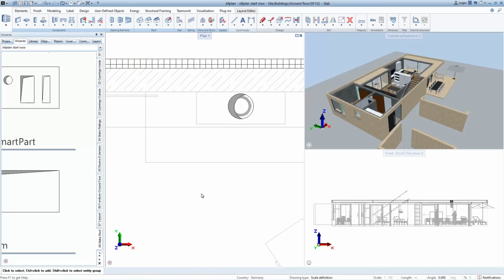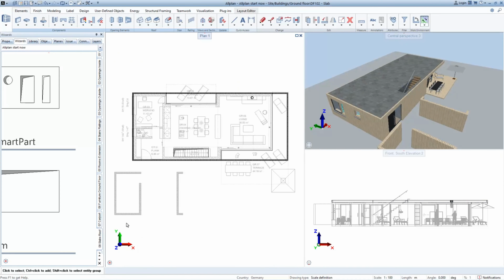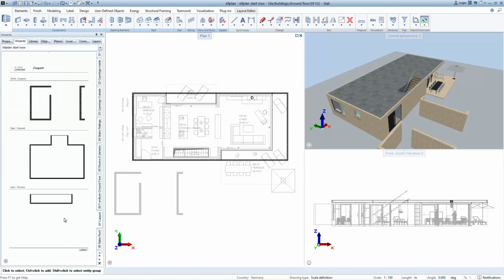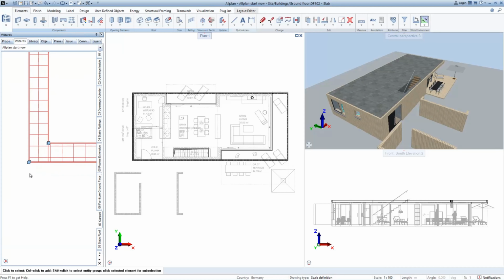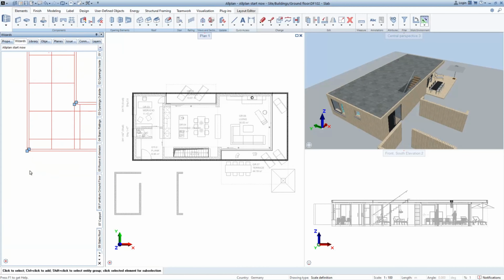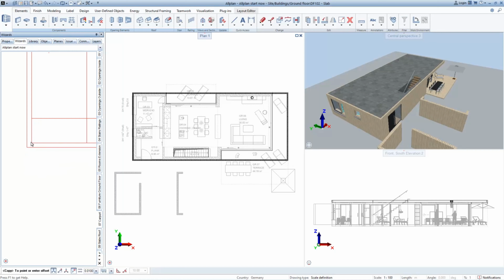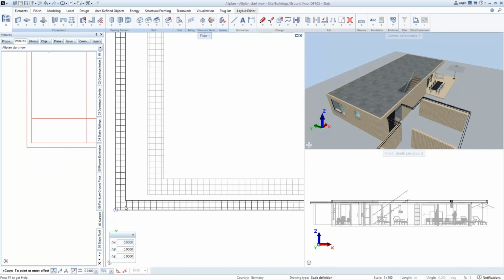The slab carport and the roofing terrace can be copied from the wizard. In the 07 carport wizard, the carport roof is marked and zoomed in at the bottom left of the wizard. Alternatively, you can start the function copy and paste and mark the roof carport in the wizard. The best anchor point is the lower left corner of the wall.